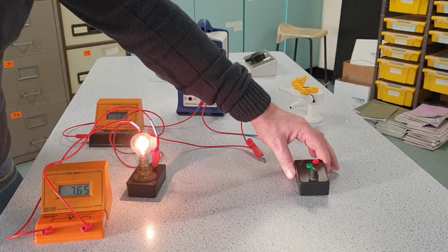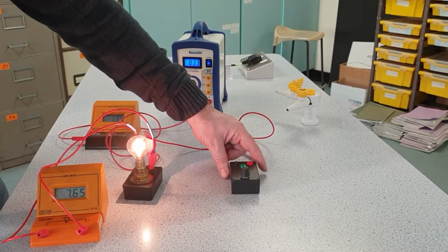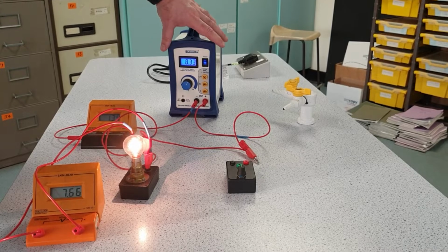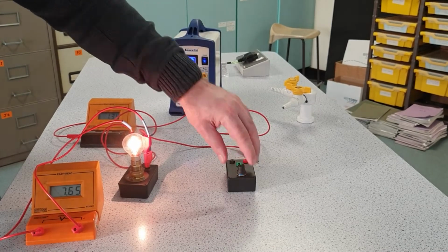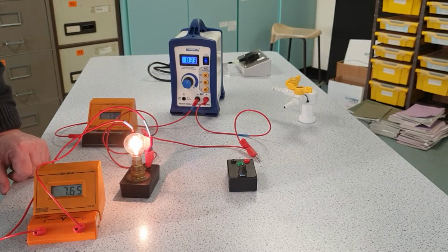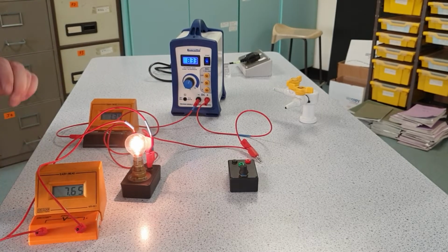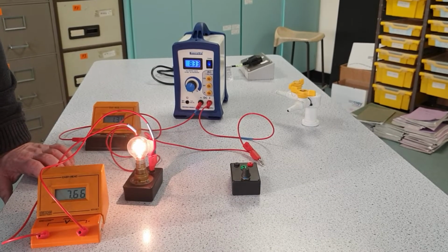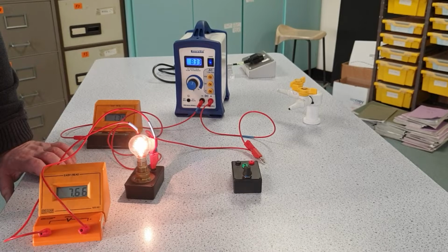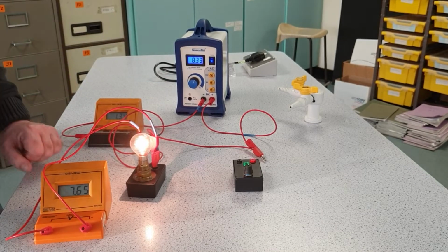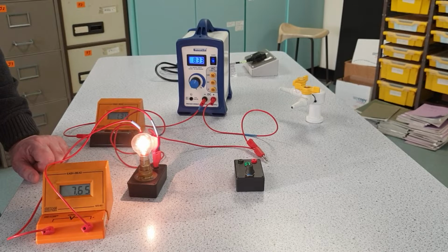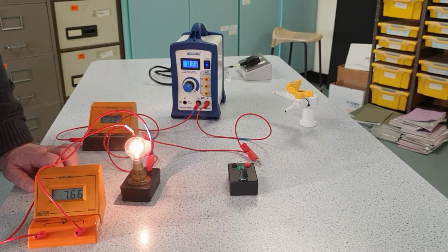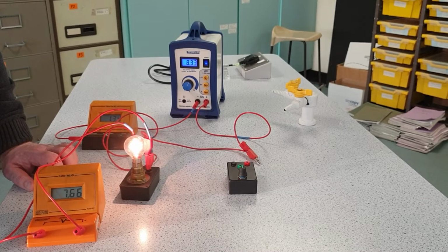The only thing is you will need to learn about variable resistors, because you might not have a power pack, you might just have a cell, which you can't change the output of. So you might need the variable resistor to change the voltage across the light bulb. Okay, so that's the actual experiment. What about the results of the experiment? Now that's the important thing, because there are 3 different components that you might be asked to test with an experiment like this. You might be asked to test a light bulb, you might be asked to test a fixed resistor, and you might be asked to test a diode.